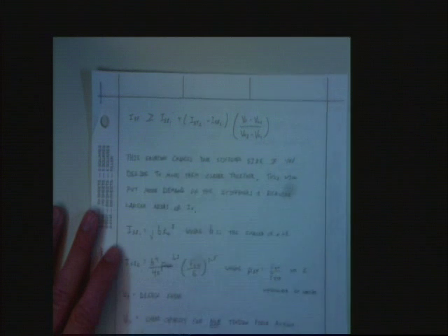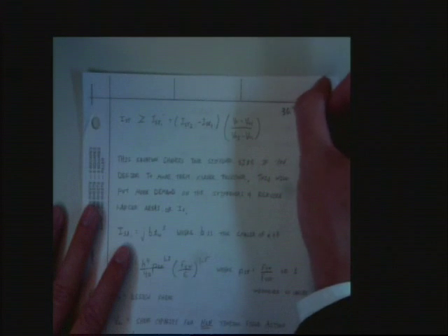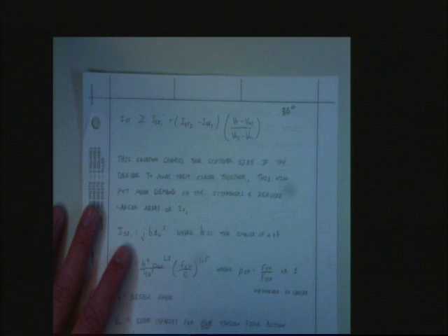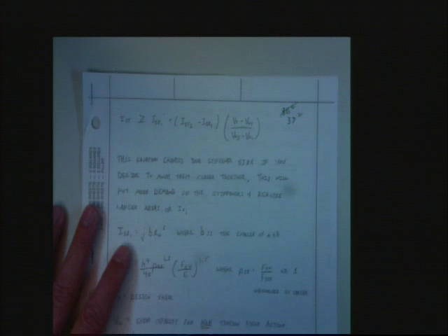So let's say you did some calculations. We're going to work an example problem that's going to show you. Let's say you did some calculations and you found out you needed a stiffener spacing of 36 inches. Or let's just say it said 37 inches. And what did you choose? You chose 36, because it's much easier to lay out 36 than it is 37.